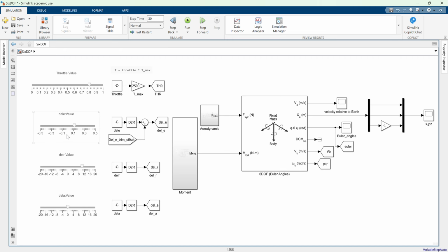So that looks good. And before I initiate any test, let me make sure that my rudder is neutral and aileron is almost neutral, because I don't want any lateral directional dynamics to affect me at this point. And throttle, since my max is 2500, I will just take it about 1400 off that. So there is the fractional reduction.